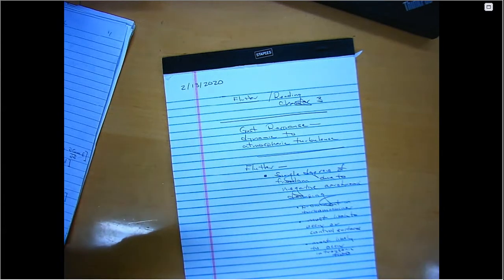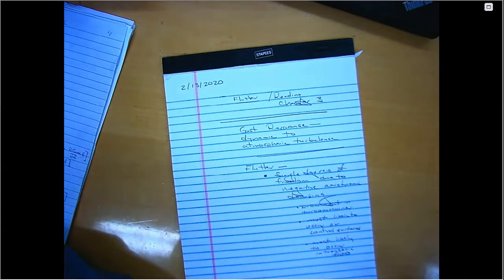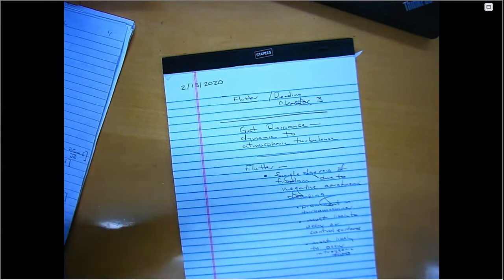So if I'm doing an analysis before they really define the airplane, it's a paper airplane, right? You're thinking about a new airplane. You have a vague notion what it's going to look like, and maybe how many engines are going to be on it. You have a rough idea of what Mach number you want to fly and so forth. I'll probably do a lot of 1 and 2 degree of freedom flutter analysis, except it's a ballpark answer.